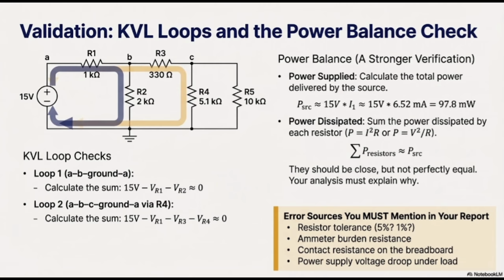So let's talk about the KVL, our beloved KVL. Again, what does it say? The KVL says that the accumulation of all of the voltages inside one loop or one mesh is going to be zero, and it doesn't matter. As long as you have the closed path, your KVL should be zero. KVL means that the combination of the voltage rises, which we have because of the voltage source, and the voltage drops, which we have for the components, should be zero.